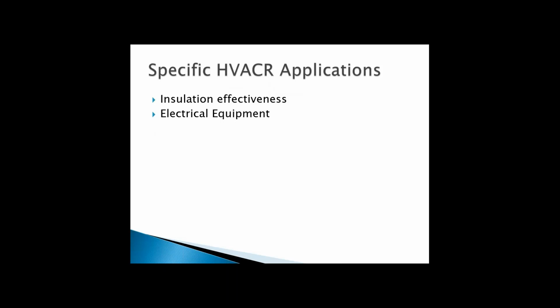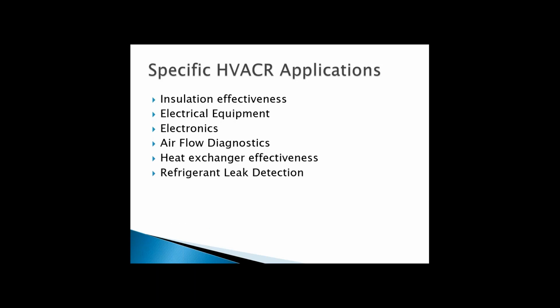Electrical equipment, like we just showed. Electronics. Airflow diagnostics. Even though ductwork would be a thermal mirror, you would be able to see the air coming out of seams that have not been sealed properly. Another really good use is heat exchanger effectiveness. Refrigerant leak detection. Steam and hot water heating. These are extremely useful for looking at steam traps to verify that they're operating properly.